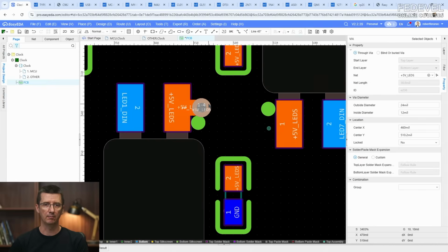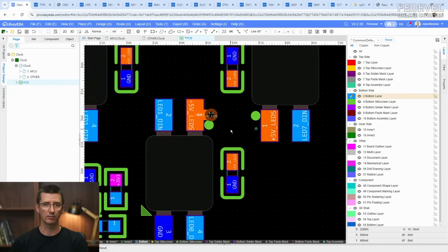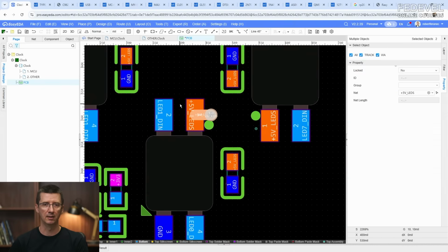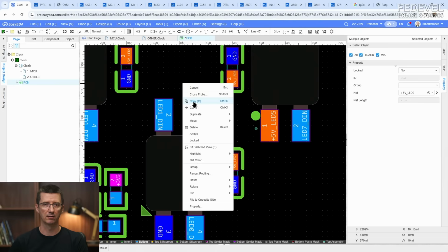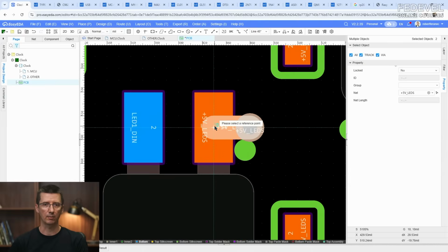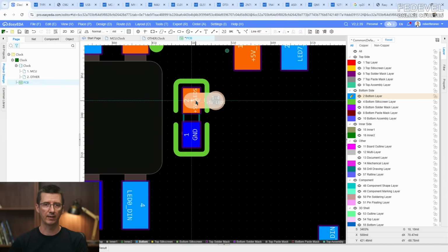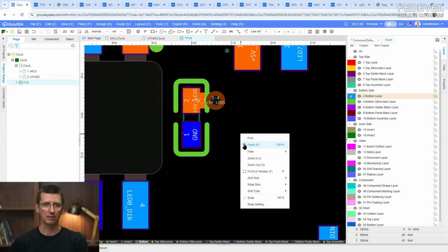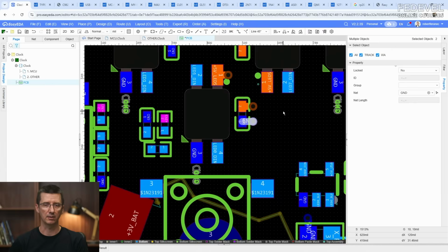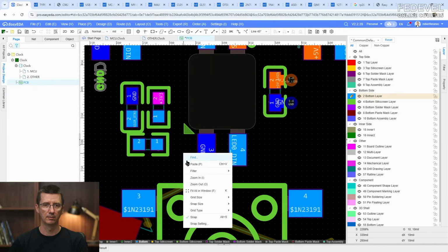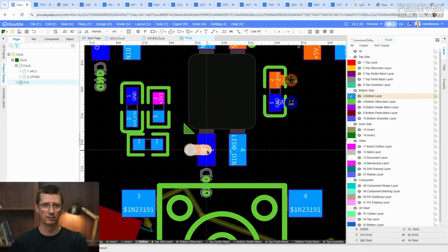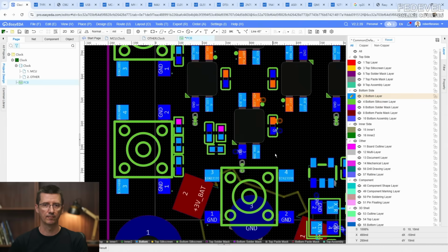So via makes the connection between layers in PCB. This is the size 2412. Be sure we are using exactly same size for vias. I'm going to copy this, pick it up where the path is, and place it also on the other pins. Do it like this.